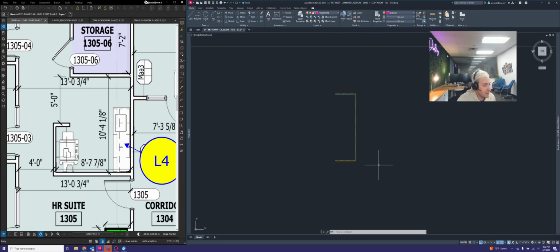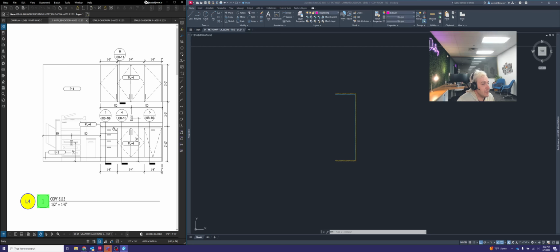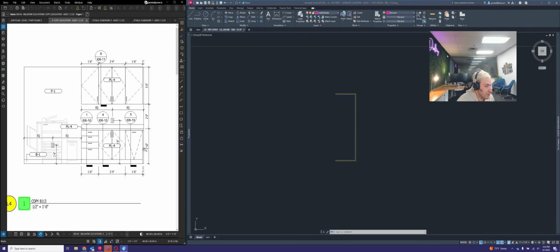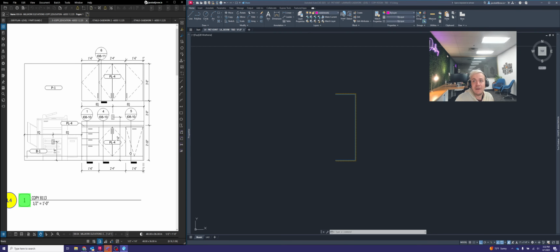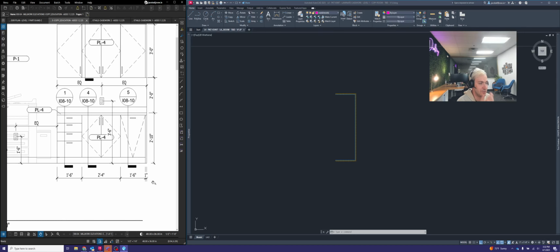All right, so countertop. Well, they don't give us the dimension on the countertop here. We kind of have to figure that out. So we're going to go back to our elevation view to determine that. And what we need to do is kind of go back here, add up these dimensions, and then try to also include that 1/4 inch overhang.